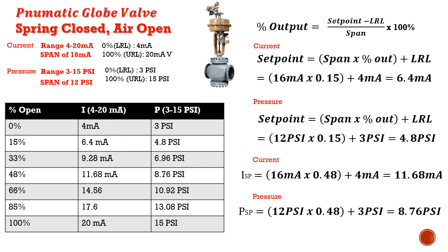You can put that into an algorithm in your PLC, so as your feedback loop comes back, you know if you need to adjust a temperature by blending liquids in. You can say, I'm at this percent open, I need a bit more, so you can throttle the valve open more. Or I'm at this percent open, I need less, and so you can throttle it back.